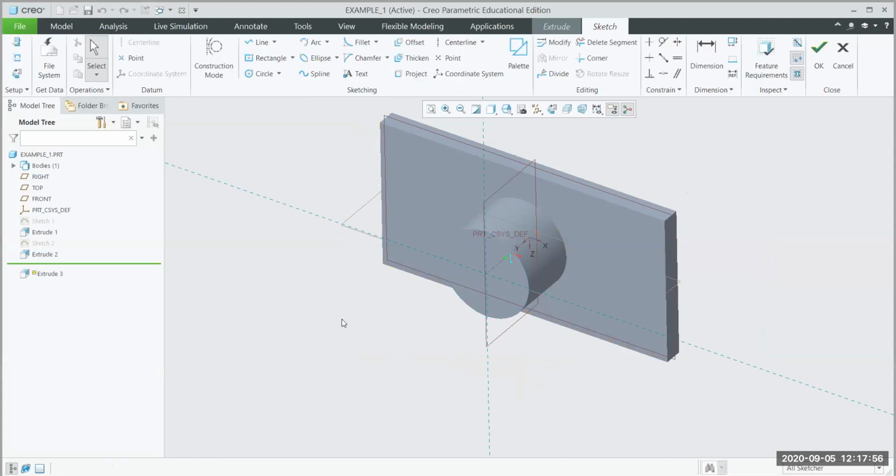All right, I went ahead and selected extrude to get me onto this surface here. I'm going to select circle, center point. Okay, now hit your middle scroll wheel, push it down, double click on the dimension. I'm going to make this 15, and I'm going to hit OK.